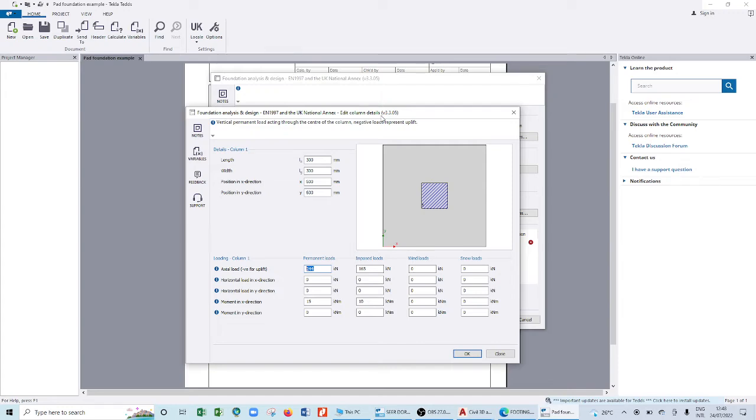So now, when you come back here, you have your permanent loading, which we have got as 32.3. Then we have your imposed load. Those are the actual loads that are coming. It is 12.5. Now, when you check on the tab, it is also giving you an option of a horizontal load.